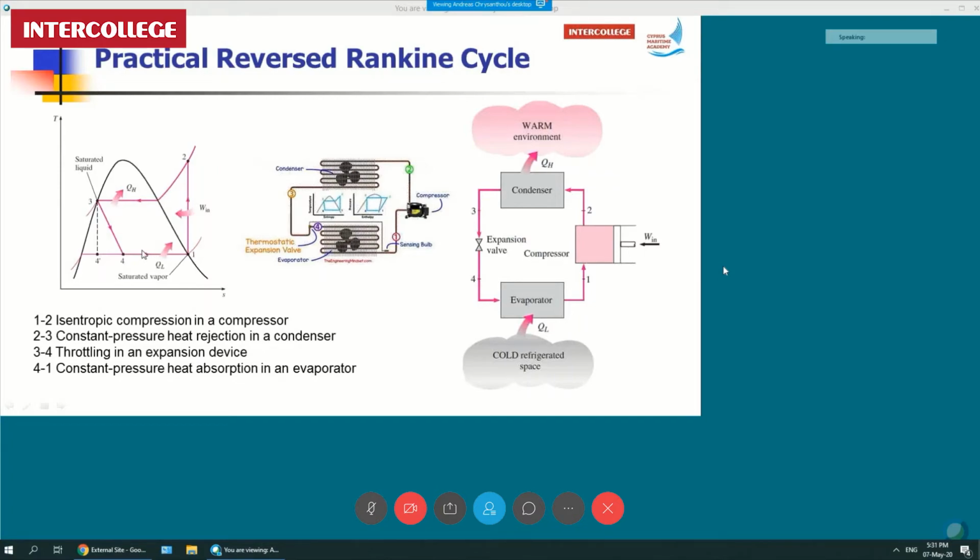And again, like before, as in the Rankine cycle, the reversed Rankine cycle, or vapor compression cycle as it's called, we push all this for the compressor into the gaseous region. Then we condense down into the condenser. Then we have to go all the way down to the liquid stage to have the expansion valve. There is the liquid stage, where we have the expansion device, and then we have the evaporator.